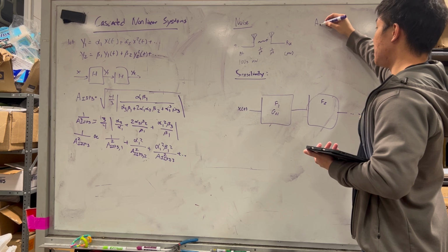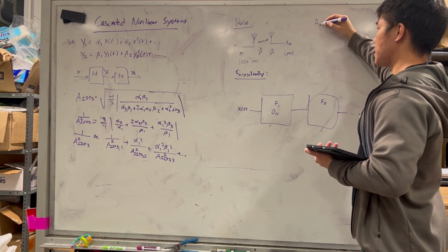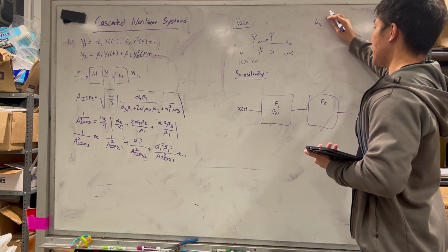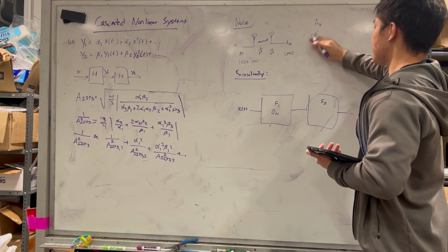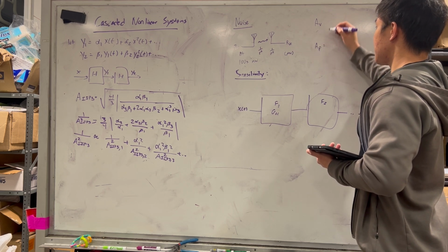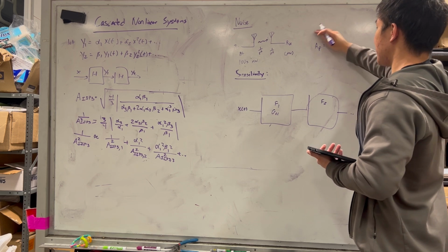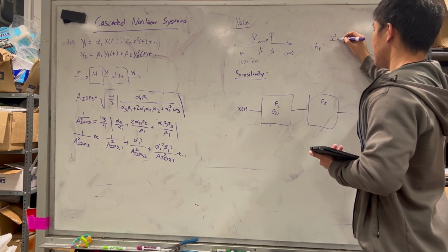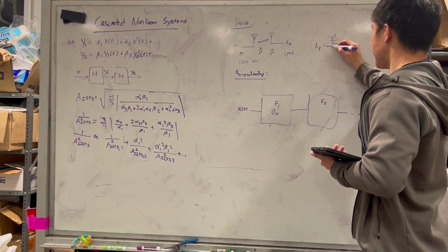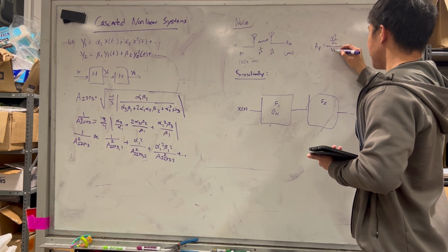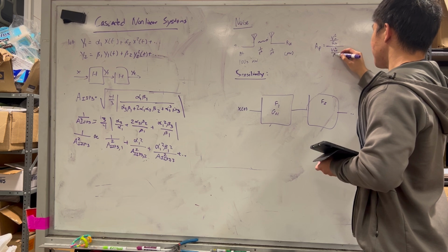Yeah, so I think I talked about this at some point, but let's say voltage gain versus power gain, right? I can talk about just power gain. Power gain is V out squared over R out, over V in squared over RS.